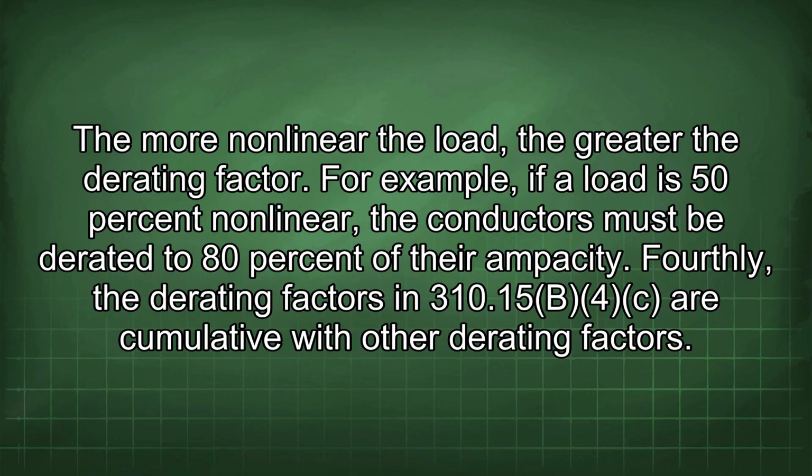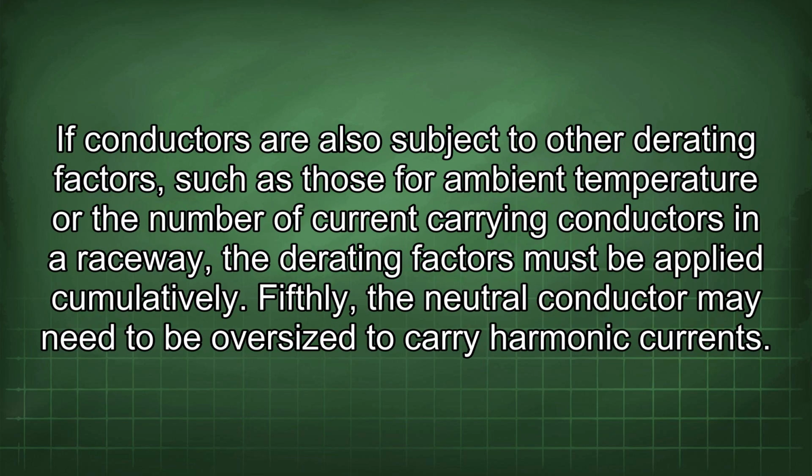Fourthly, the derating factors in 310.15(B) are cumulative with other derating factors. If conductors are also subject to other derating factors, such as those for ambient temperature or the number of current-carrying conductors in a raceway, the derating factors must be applied cumulatively.